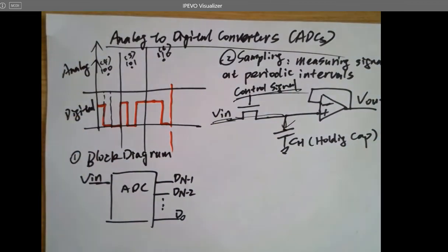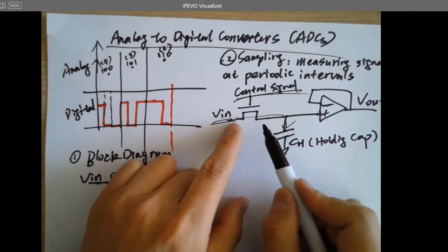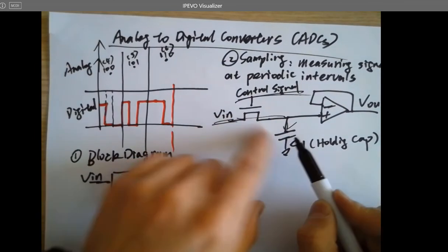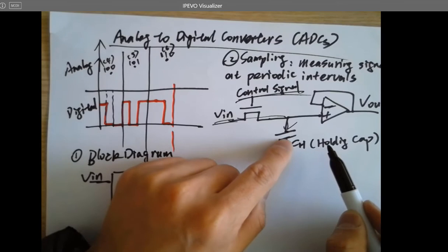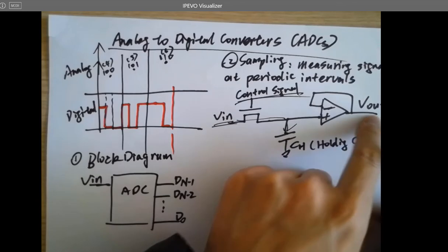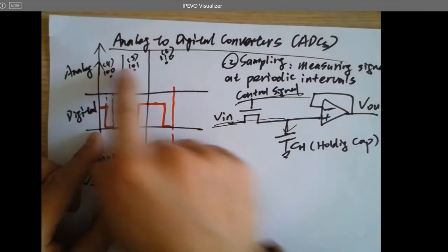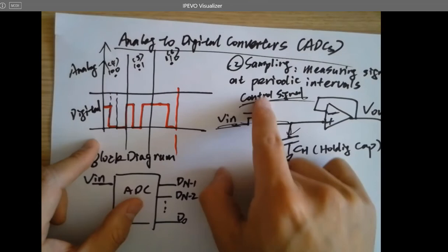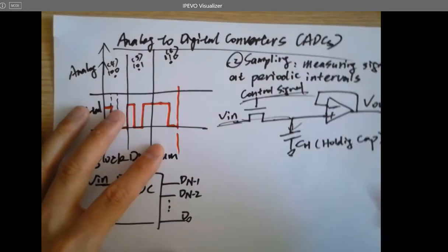I just sample. So we have a continuous analog signal, but it cannot sample all the points. Is that making sense? Right. So you are not a Superman. You cannot sample all the points. You definitely have a sampling frequency, and you want to sample it as quickly as possible. In general, you open it really quickly and then close the switch, and then the charges will be dumped into the cap, and the voltage will appear here. So that's one analog point, one analog value here. For example, this value 4 will appear here after you sample and hold. So it's called the sample and hold circuit.